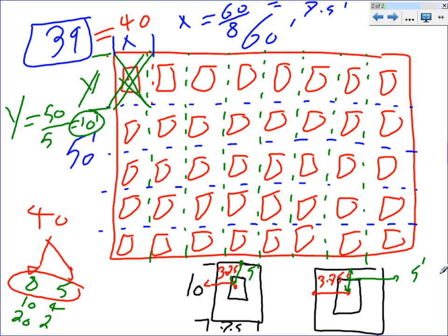Any questions, guys? And really, there's no right or wrong. Mr. Bu, you could have said, I'm going to go by 10x4 and do your design by 10x4. I assure you, the closer the number of the columns to the number of the rows, the better lighting distribution system you're going to have, meaning the smaller the ratio between the maximum, the brightest spot in your room, and the minimum, the darkest spot in your room.